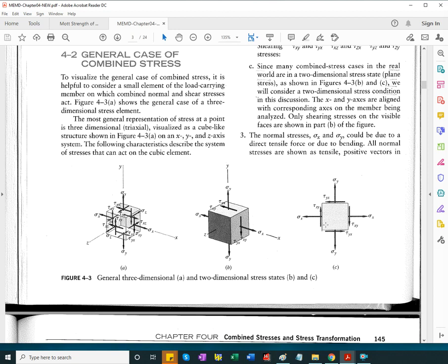And then we have the normal stresses. Okay, so tensile, tensile, tensile, tensile. This could be the case easily of a pressurized pipe. So due to the internal pressure, I have what will be, so assuming the pipe has the axis, x-axis, and very important, we choose the stress elements in a way that makes our analysis easier, to where the element is aligned with the geometric axis of the part.